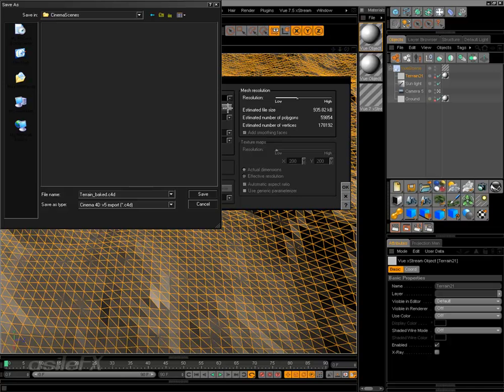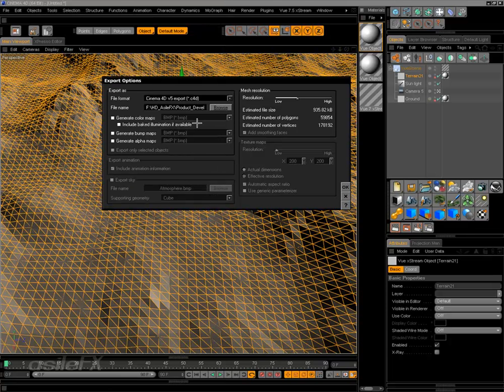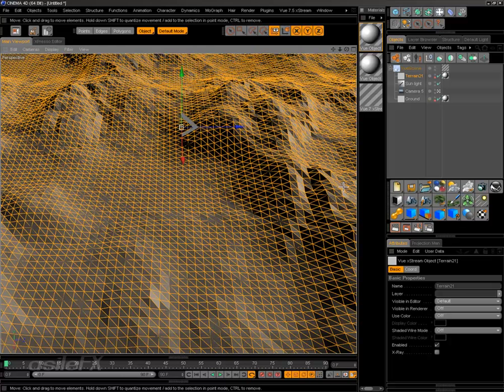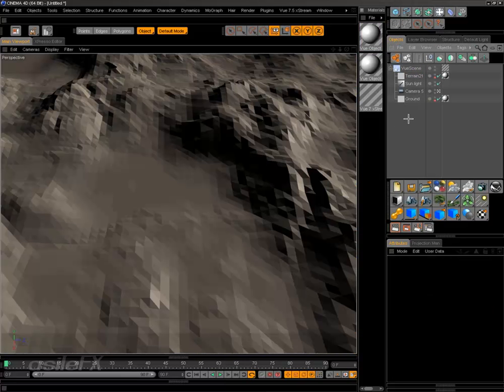And then you also want to make sure that you're selecting the file type within the save options in the window. Otherwise it will reset and by default set to a 3ds file. So no matter what the file format option you have set, when you click browse to choose your directory, it will reset that. So now we can click OK. The only thing that's going to happen is we're probably going to end up with a little bit of a scale change, so we'll have to take a look at that.